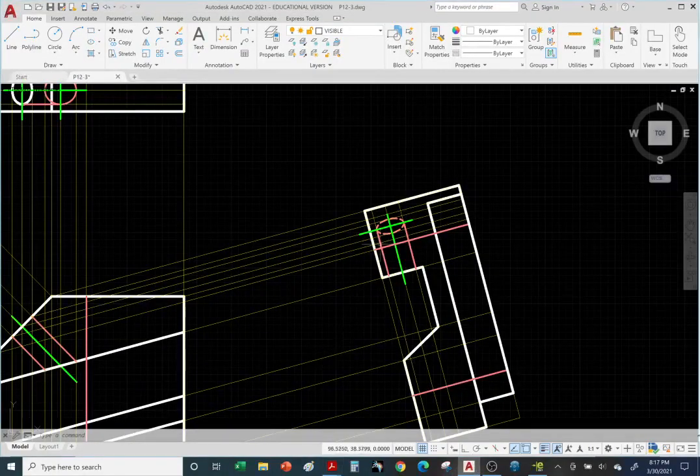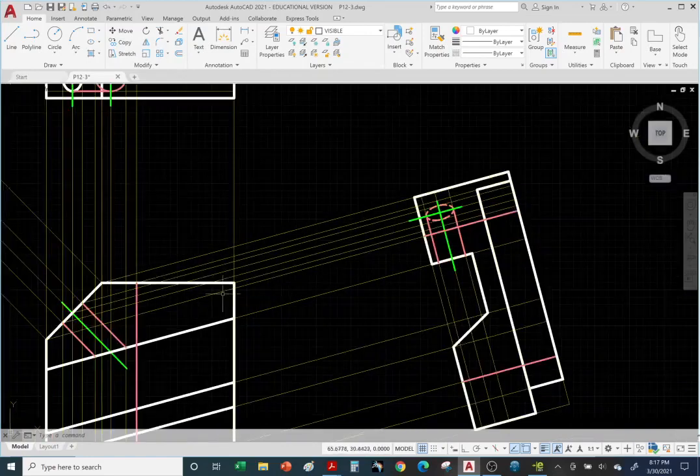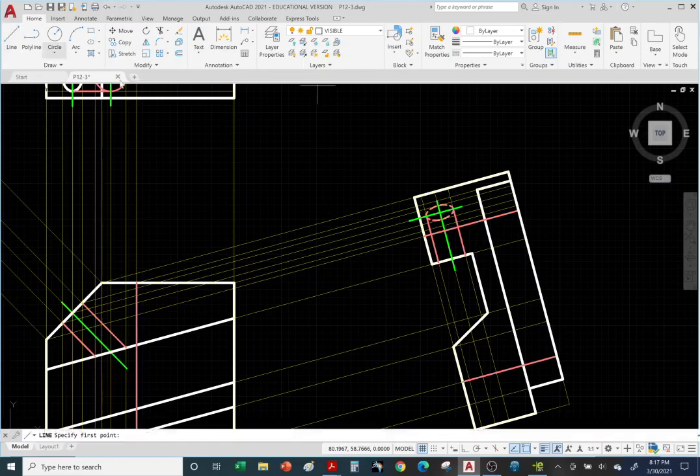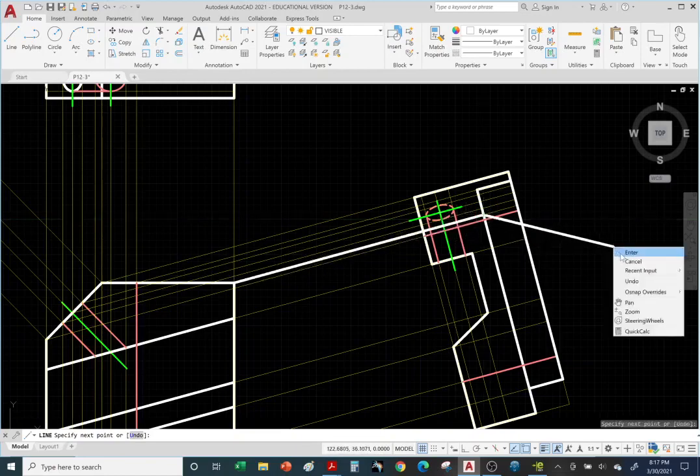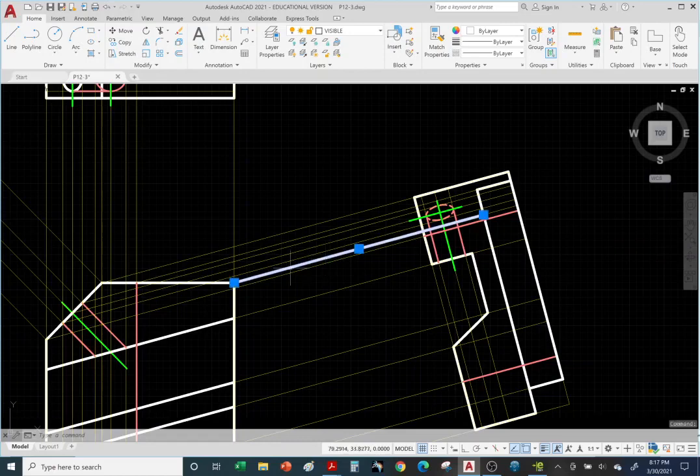And I actually did miss the wide visible object line here. All right, so it's with respect to this corner. So let's draw that wide visible object line from this vertex. Follow the parallel lines, right? And it ends here. Right click enter. And now we can shorten it. Okay, hit escape on the keyboard to deselect. Okay, there we have it. Okay, I think we have everything now.